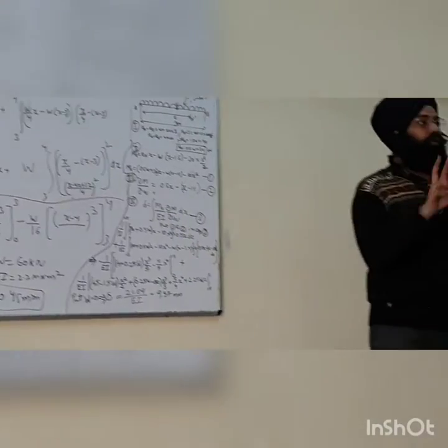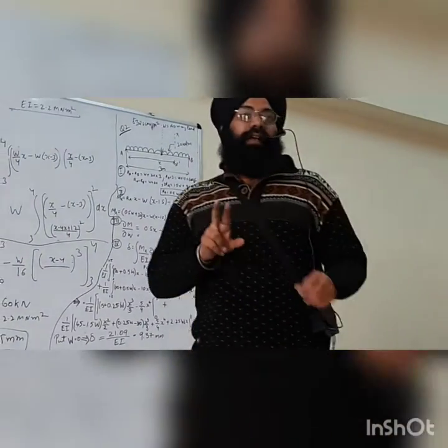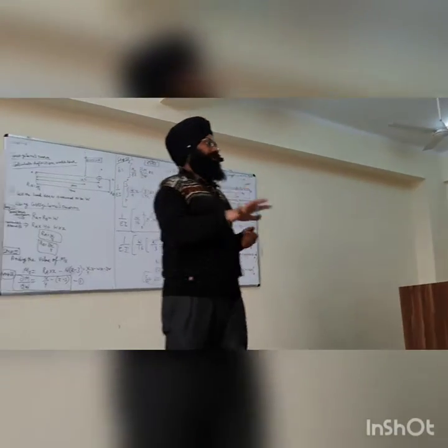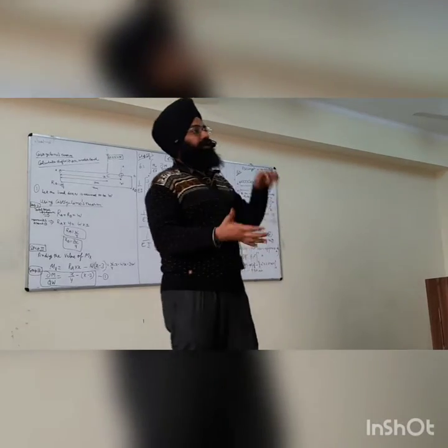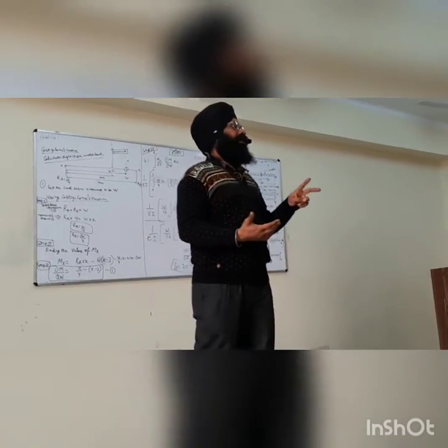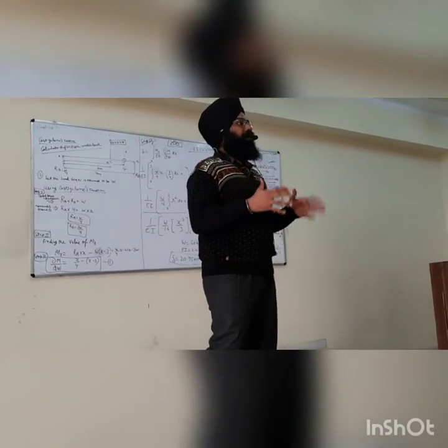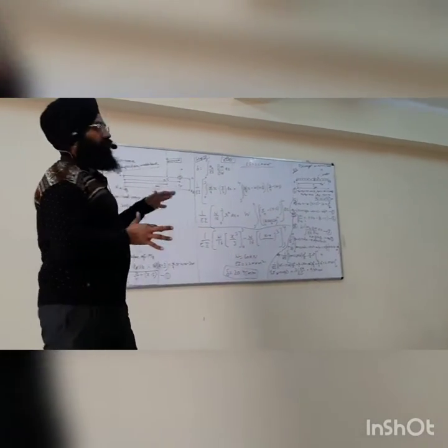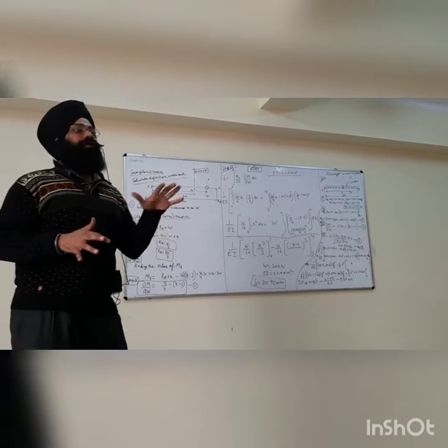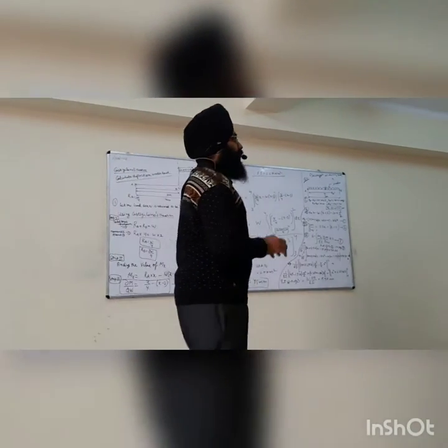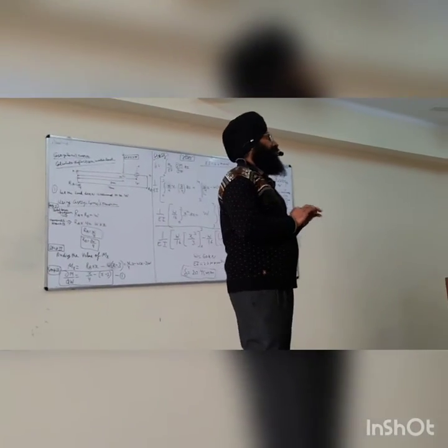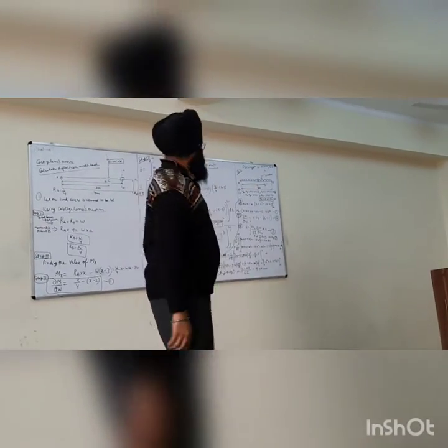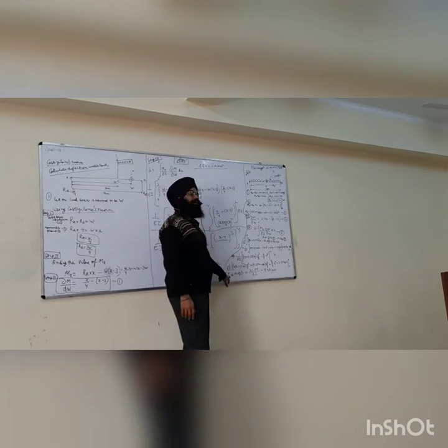So these were the 2 cases of calculating the deflection of a beam using Castigliano theorem. One was the simply supported beam with a point load. The second was the simply supported beam with a uniformly distributed load. In these 2 cases, you have to follow 5 simple steps to calculate the deflection. Just keep one thing in mind: whenever you put a dummy load on your own, you have to put that value as 0 at the end.